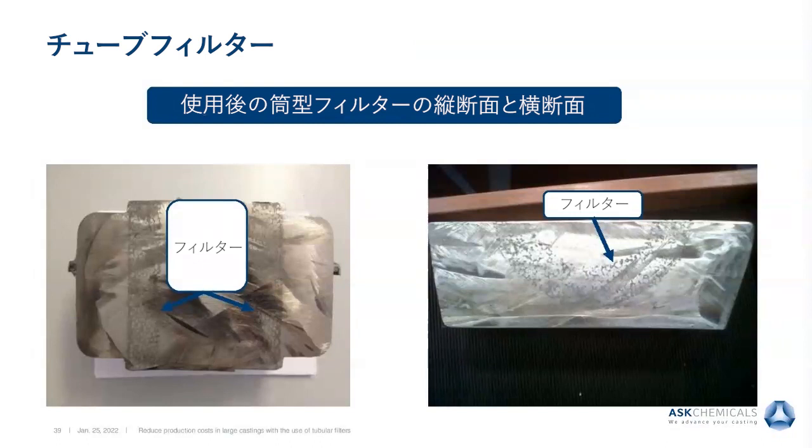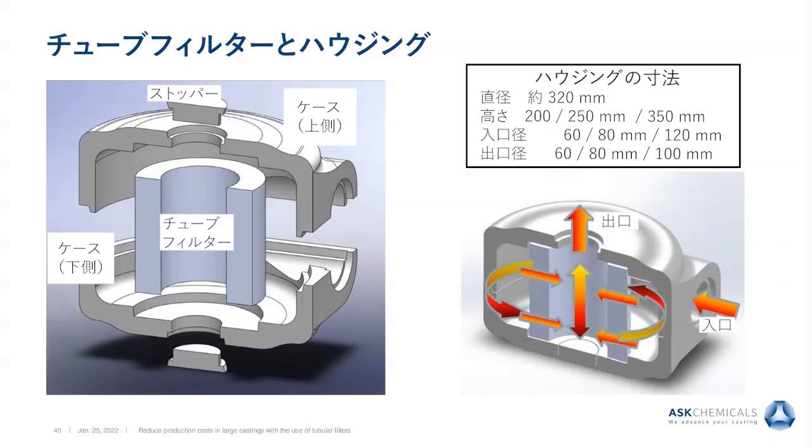The geometric shape of a tube is a very efficient design. The tubular filter allows molten metal to flow through from the outside to the inside, which means the entire hydrodynamic and ferrostatic pressure is on the surface of the filter, and thus acts on the ideal self-supporting geometry. The destruction of the filter by fracture is greatly reduced. This way leads to a new dimension in the use of ceramic foam filters.